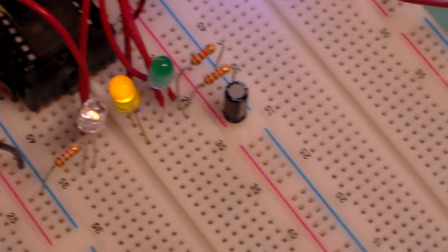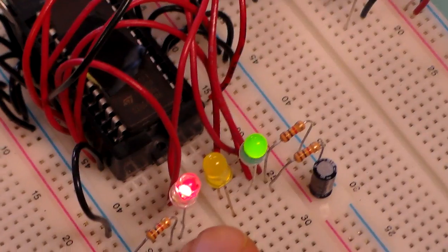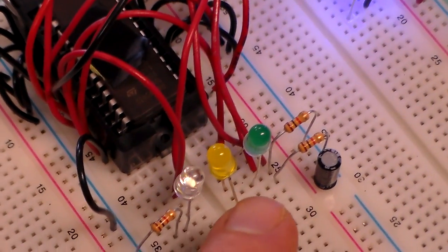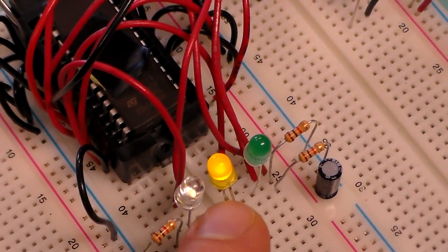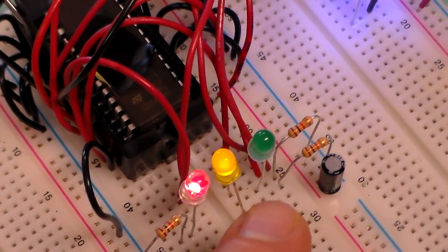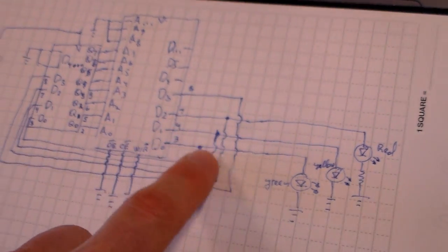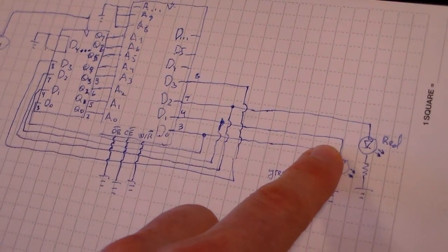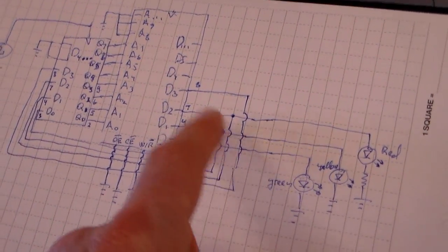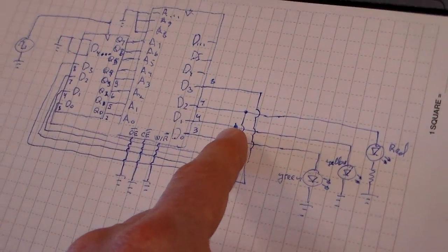So what happens when you take a look at the LEDs is that they appear to count 1, 2, 3, 4, 5, 5, and then 6, 7. 0, 1, 2, 3, 4, 5, 5, 6, 7. So that extra bit here that gets recycled as part of the next address, but is not illuminating an LED, helps us to duplicate the output of 5, the 101 here that we saw for 2 clock pulses.